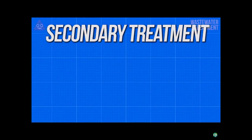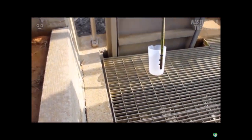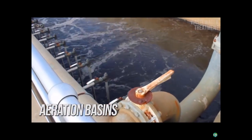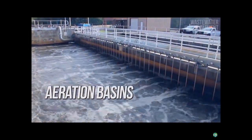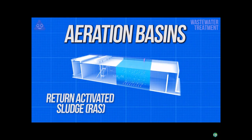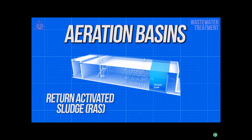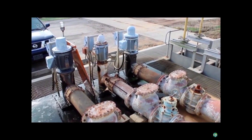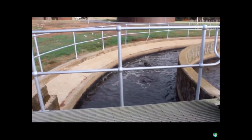In many cases, this process starts with aeration basins. Effluent flows into the aeration basins, at the bottom of which are hundreds, if not thousands, of tiny air blowers that create bubbles through the water. The water is pumped into this tank along with something called return-activated sludge. You can think of return-activated sludge as a bunch of happy little bacteria that get to eat their favorite foods all day long. This introduction of significant amounts of bacteria along with the massive amounts of oxygen injected from the bubblers creates an environment perfect for the process of aerobic digestion. Summarized simply, it's the breakdown of organic matter along with the use of excess oxygen.